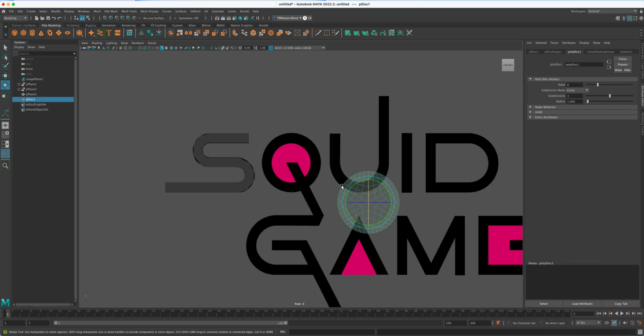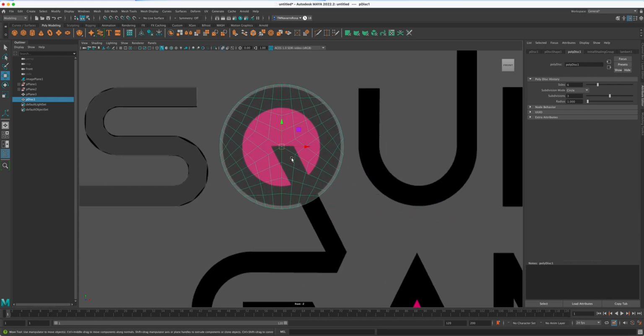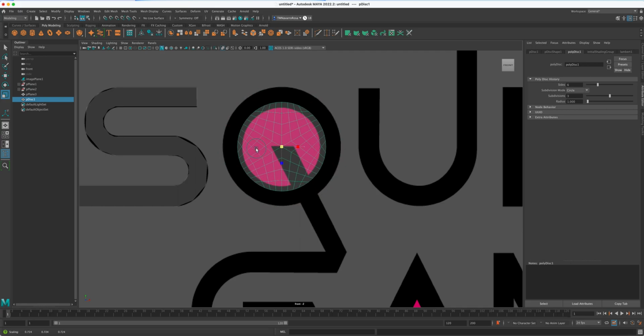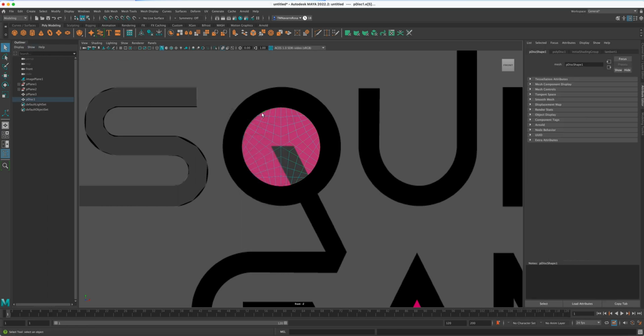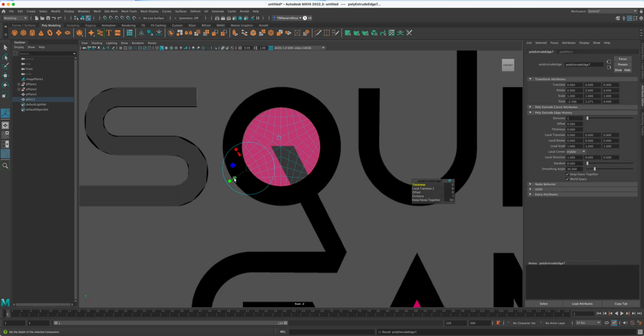The important part here is this. So W, pop it around the O, zoom in to make sure that you have a good view. We're gonna press R, get it right in the middle. Let's move it around till we perfect this. I'm happy with that. I'm gonna select the edges, double clicking, Command E, and I'm gonna pull here.